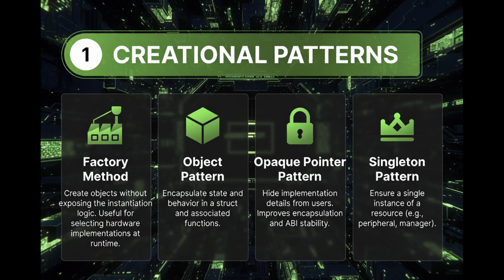In embedded systems, this is extremely useful for sensor selection, PHY detection, flash chip detection, board variants, and protocol driver loading. For example, a bootloader may detect whether the board uses a Micron flash or a Samsung flash or an Intel flash and dynamically return the correct driver implementation. This enables hardware portability, cleaner initialization, reduced coupling, and scalable platform support.